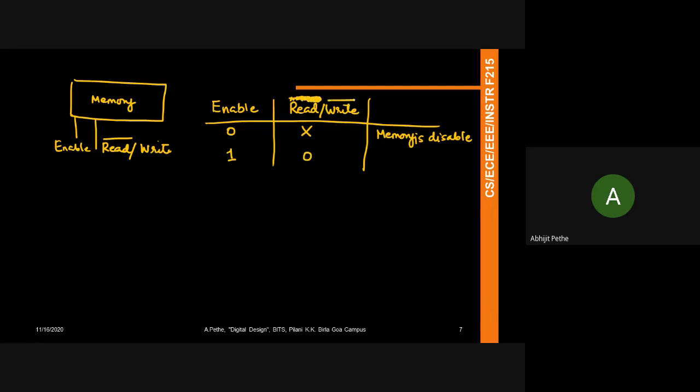Let's call this, right? So when this port goes to 0, it says write to the selected word, and this is because I assume that the address is available on the address line. So when address is available on address lines, before I do all this, I will ensure that address is ready.